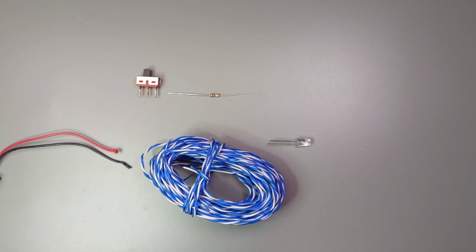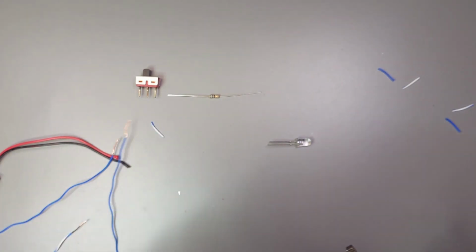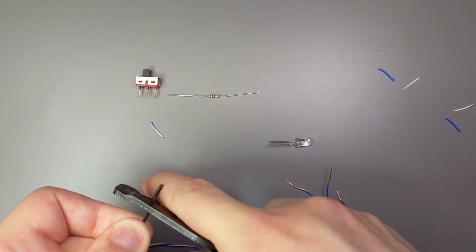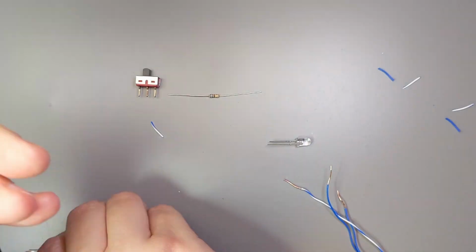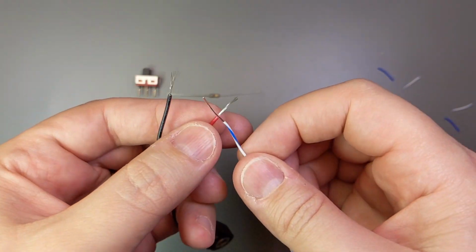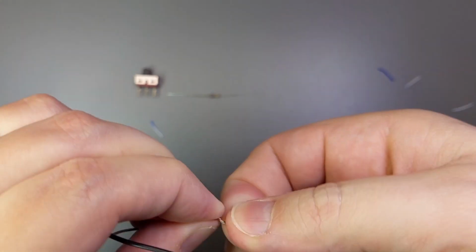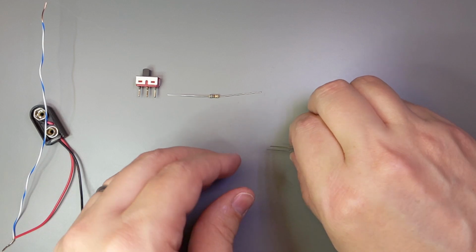I'll use some wire that I pulled out of some spare Cat6 network cable. It's solid core and easy to work with for little projects like this. I chose not to solder any of these connections just to show that it can be done. It's better to solder your joints for electrical connectivity and physical strength. However, I can say that twisting wires together and some electrical tape can work pretty well in many circumstances.